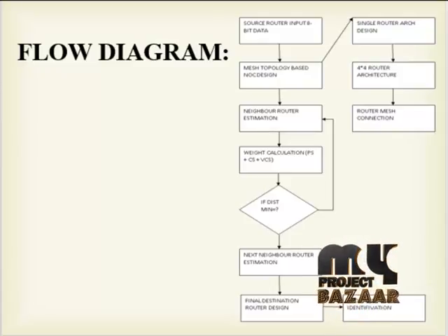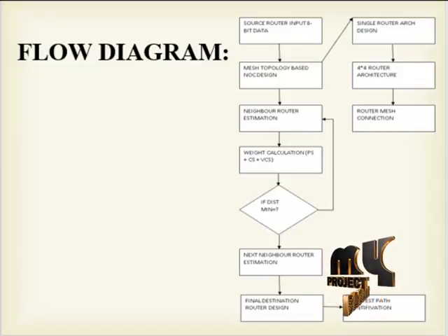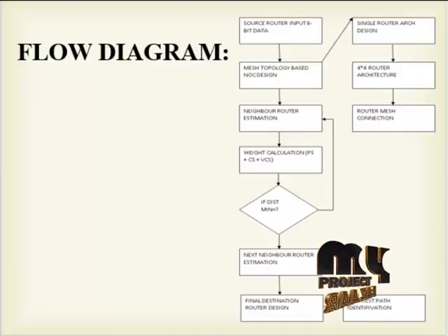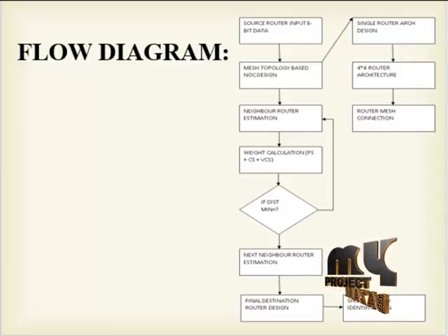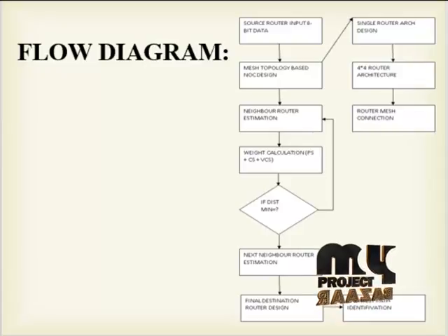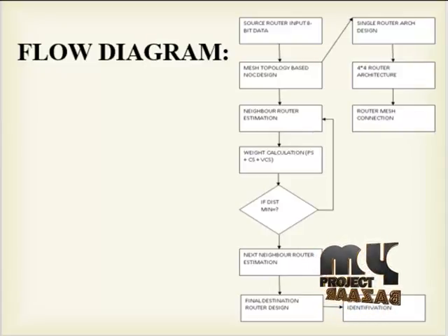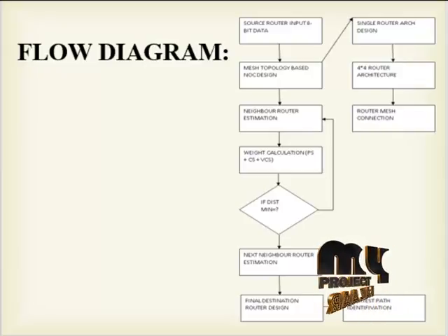The router section is used to maintain the signal energy level due to the long data transmission process. In our process, we design the four-port router architecture and apply mesh topology connections between the four-port NoC designs. The four-port NoC design reduces the energy consumption level for inter and intra chip communication. So we use weighted bit calculation for every router placement position in the four-port NoC designs, and then go to the neighboring router estimation process.